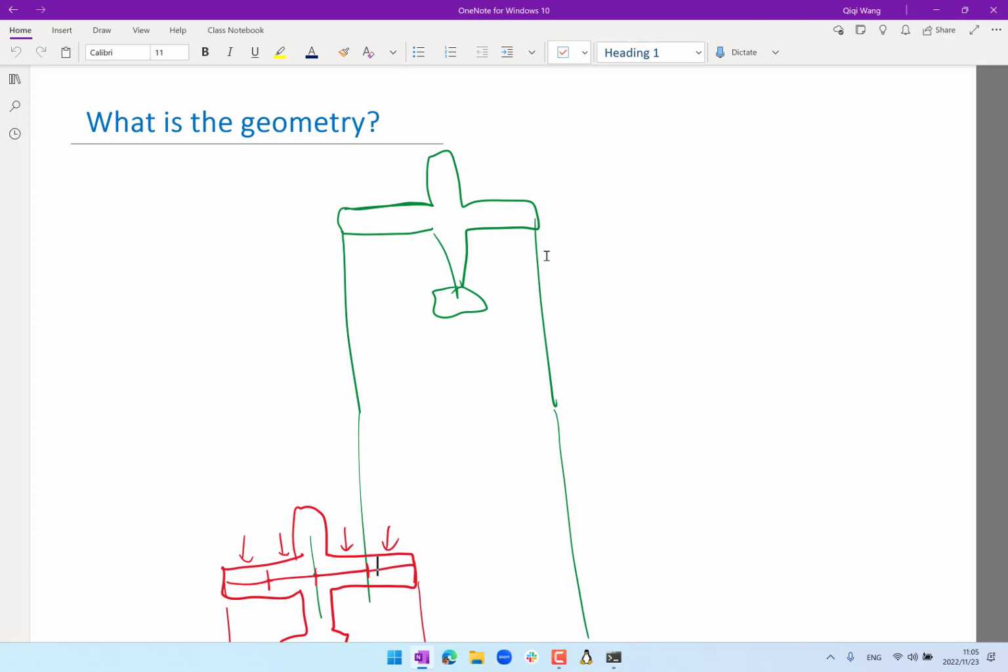And so far, total drag is just equal to the skin friction drag plus wave drag, which we said is negligible for the airlines flying at that speed, right? They are designed to fly at a speed where wave drag is not a big factor yet. Okay, so wave drag, let's ignore it for now. But you may have to start looking at it when you are redesigning the wing, right? When you redesign the airplane, its shape changes.